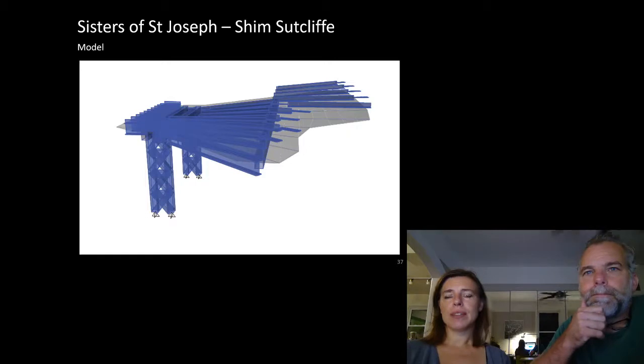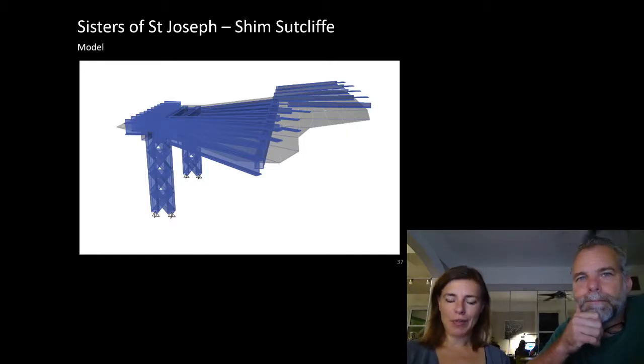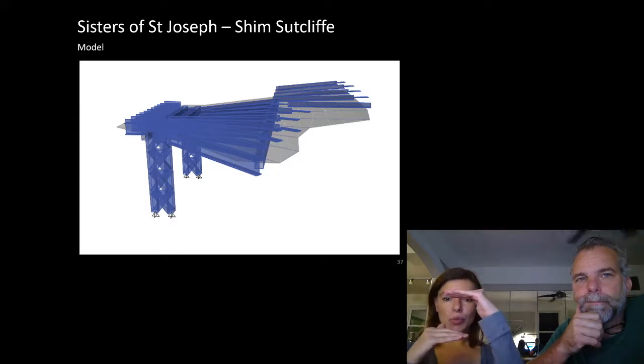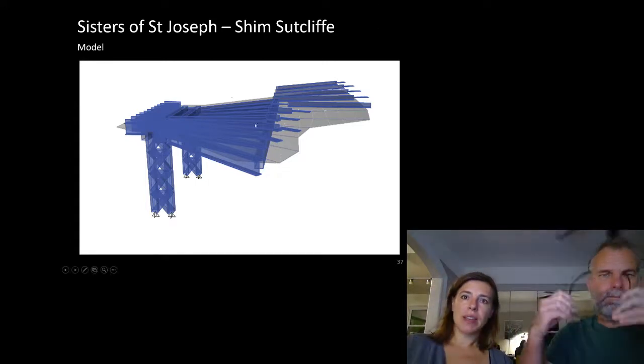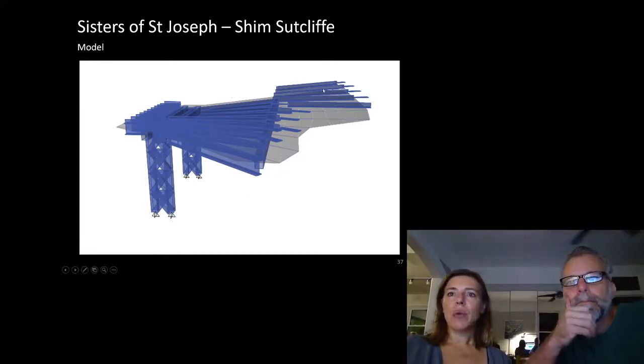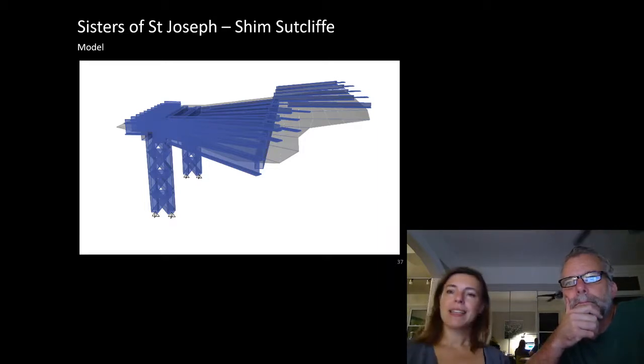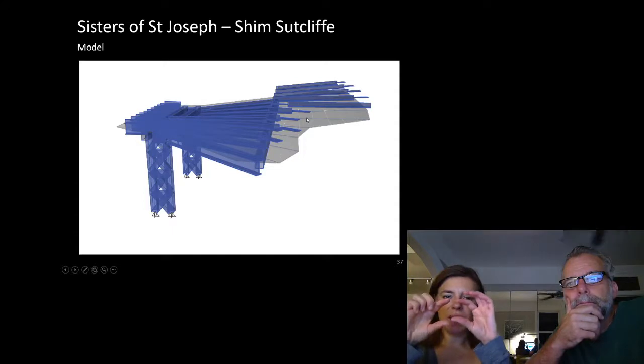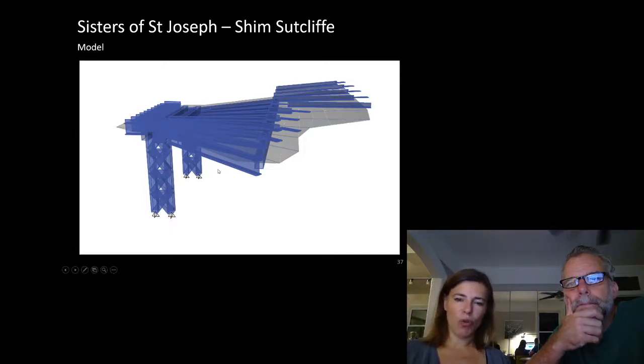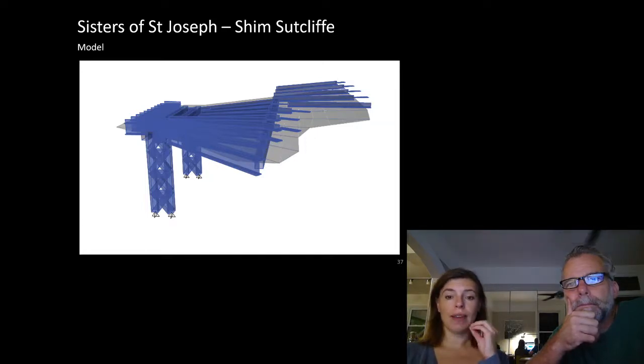This is less impressive. This is where the modeling software really starts to break down. What we had here was actually 2 plates of steel with some things embedded in it. And then out here, the modeling software doesn't like that things are on 2 different planes. And also we have elements that taper and change profile, and the modeling software isn't great with handling that. It handles it great mathematically for determining the internal loads in the element.